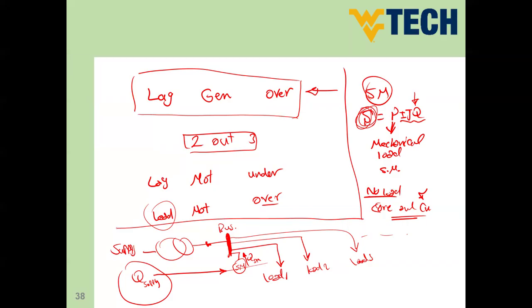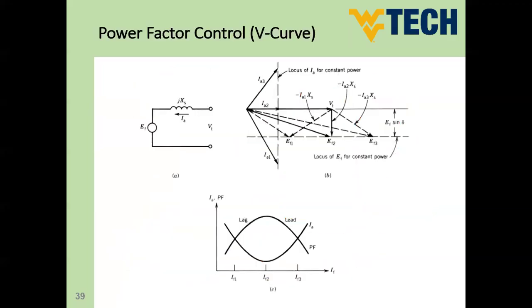And even if it is not working at all, you can just connect it to the supply in order to provide the whole capacity of apparent power as reactive power, and this would also improve the power factor. So this is one of the advantages of the synchronous motor compared to any other motor, like the induction motor.